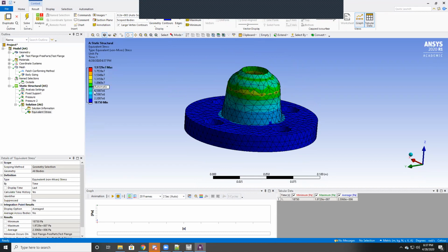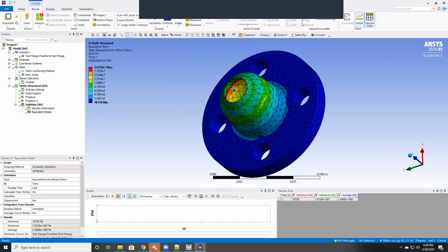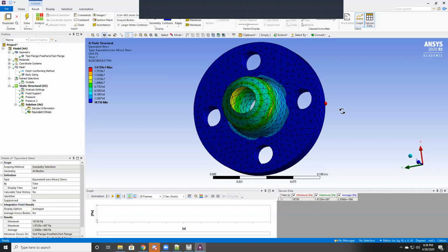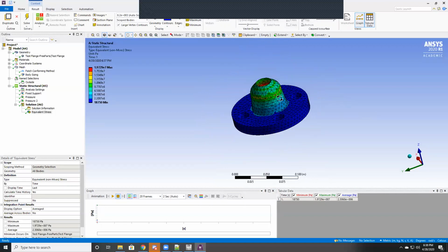We can see the scale on the left here of the pressures in pascals, or the stresses, and inside you can see that's where our maximum stress condition is, because it's right near our fixed condition where it's bulged out from that fixed condition. And so there's this really tight bend suddenly, and that's what's causing this stress concentration. Likely, if the part upstream were just as movable as this pipe, then that problem wouldn't exist. But it's just a good way to define this individual part and find its failure.